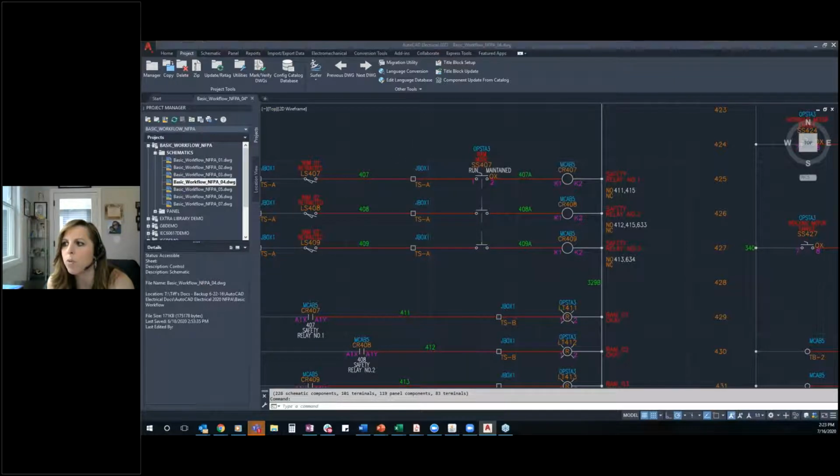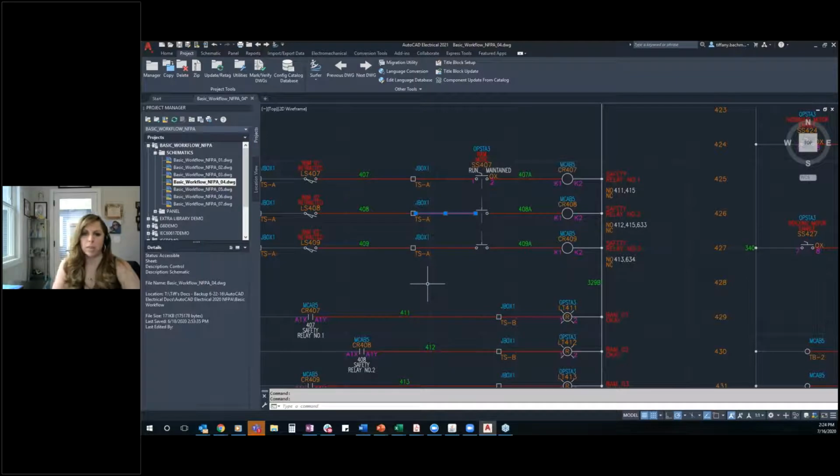The move of a wire is quite simple. You can either redraw that wire, connecting to the things you want, and just trim out the old wire. I typically don't encourage this, but you can use the grips to adjust it, as long as you make sure you actually make a connection with a connection point on the device that is going to accept that as a wire.